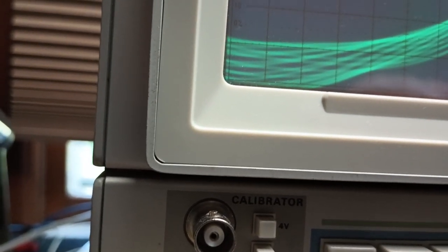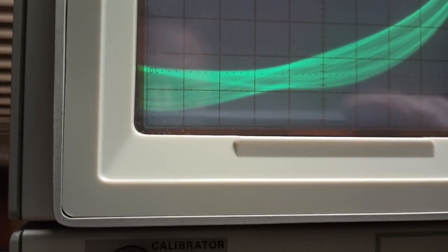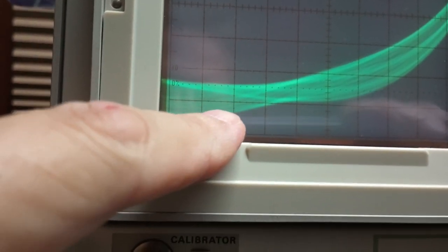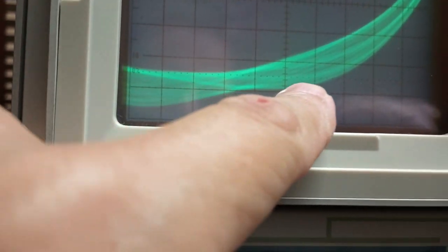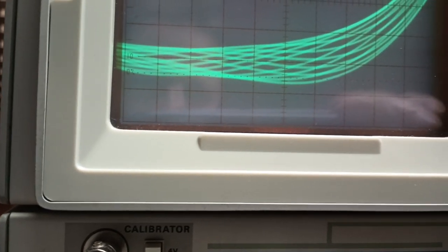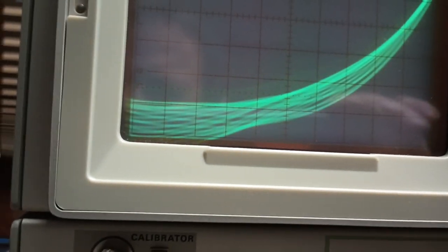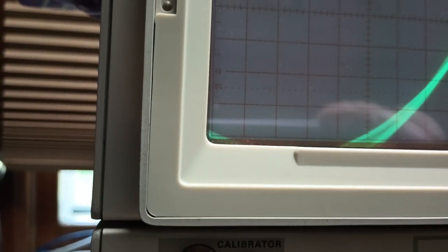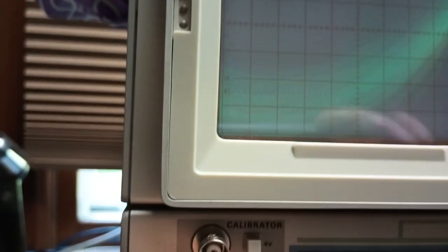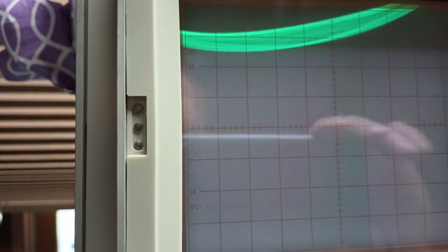A spectrum analyzer would probably show up an unusually wide trace. But you see the hump shifting. There's a shape here. And then see that bright line, there's one over here. That's the weird stuff that happens when there's mismatch. So, not good. There could be harmonics in here. I don't know what all this junk is. But up through 21.4, it kind of sort of behaves.